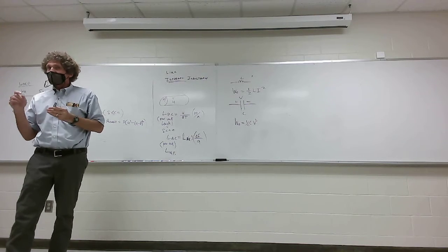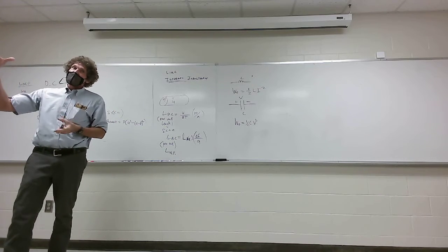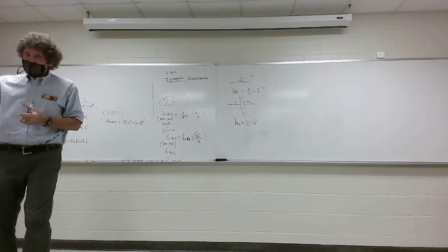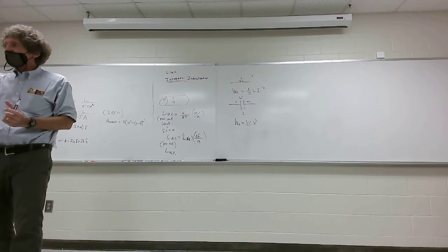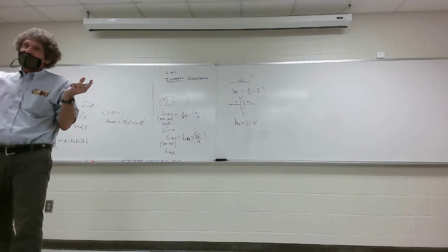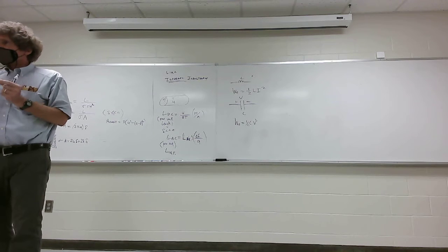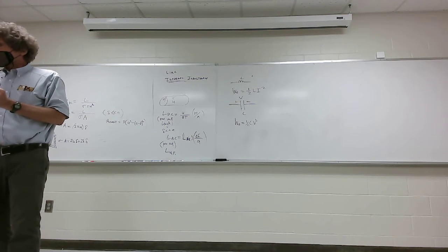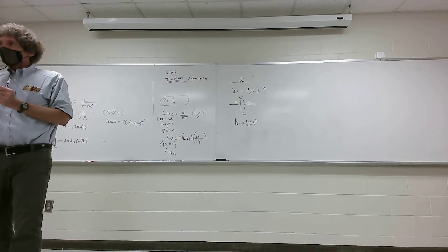And these kids, of course, used this in their best interest. We had a large inductor we had to create specifically to slow down the discharge of these capacitors so we could fire this gun. And I can't get into it all. If you discharge it instantly, all right, then basically you got a firecracker and nothing goes down the barrel. But you want a continual force as this thing's going down the barrel of a railgun. I won't get into it now, but I will later.